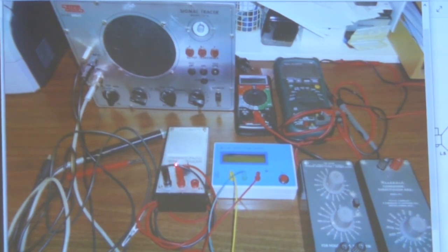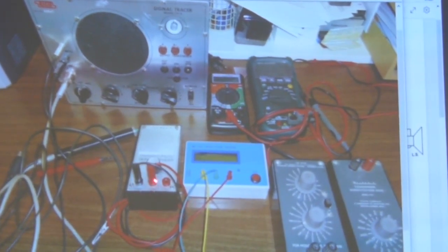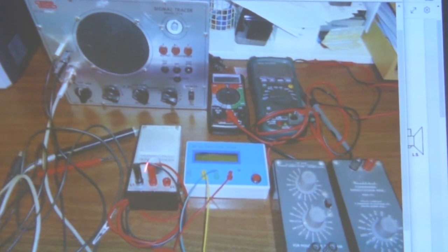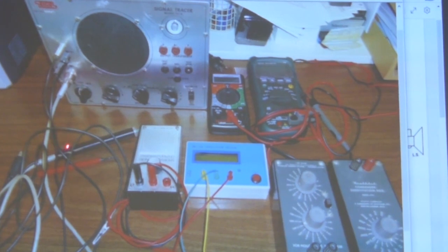And you have a volume control. The problem is if you want to use it for vacuum tube radios, you've got to watch, and you can re-engineer it a little bit yourself if you want. You've got to go in, and there's an internal diode in here, an RF detector diode. You've got to maybe reduce the signal strength at the output of the detector diode and make sure that your coupling capacitor in the input is capable of handling the voltages that might be present in a radio.